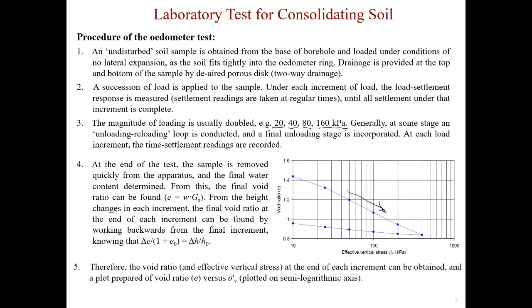So that's common sense. And then by the end of the loading, you just gradually take out some load. So the void ratio gradually increases. If you look at the vertical axis, that means there's a rebound for the soil sample. So that's the reverse of the settlement.